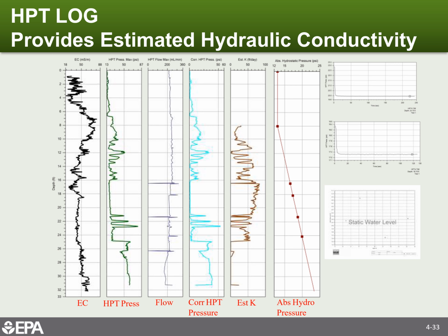And you can see, this is the top of the water table, and then the hydrostatic pressure increases as you go with depth. But then you can see this zone here that's got a fairly high hydraulic conductivity, and these little other zones here. Then you can match this up with the electrical conductivity and help you understand the hydrogeology with this tool.